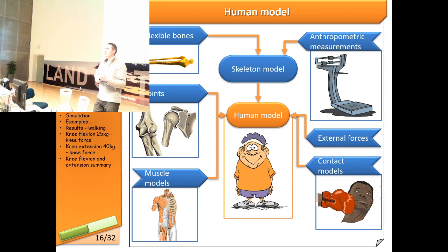But if you have some dynamic activity, then you might realize that this model might produce overly large forces to initiate or finalize the motion, and in that case it's better to use a model which is based on phenomena that are happening in the muscles, and one of the popular ones is the Hill muscle model, which links the forces and the motion of the muscle, taking into account a couple of extra activities.